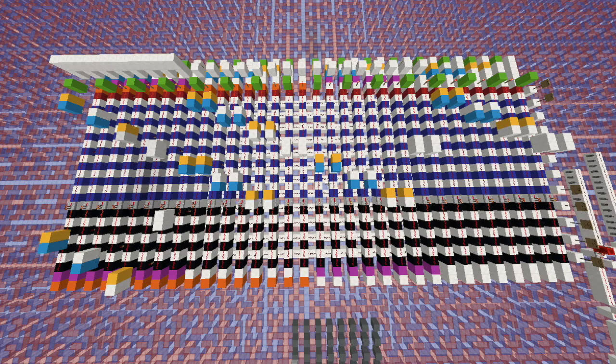And that can be done for the most part by just decoding the next 2 bits in the amount of shifting to be done. Now, one really important thing about this decoder is going to be the way that we're going to be decoding right shifts, because it's going to be a bit counterintuitive. And this is because the rotate function is technically rotate left. So the way that we create the rotate left function is that we do the shift to the left and then OR that with the overflow bits shifted to the right.